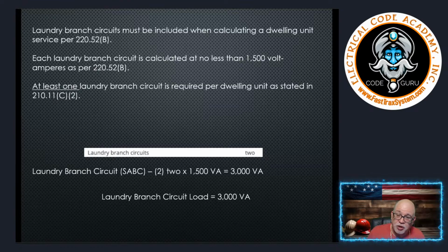Ironically, that's the same thing for cooking. I don't know if you knew that or not. I could have gas cooking and have no loads when it comes to cooking. I'm not forced to put a value in for cooking. So that's the same thing for the dryer. Now, if I do have the dryer circuit being installed and it's a 30 amp, then I have to take that into consideration. Hopefully that answered your question. All right, so we've got our value. I've already written it all down, so we're good to go there.